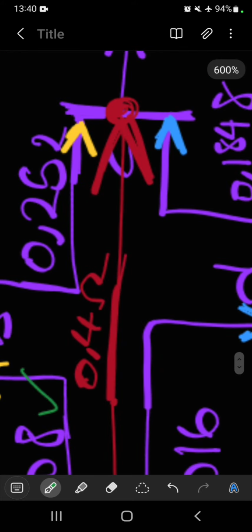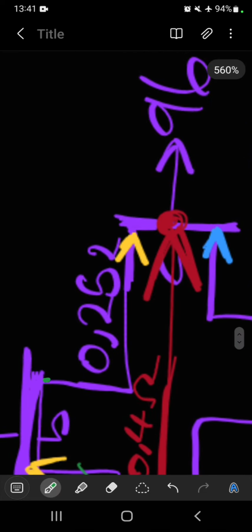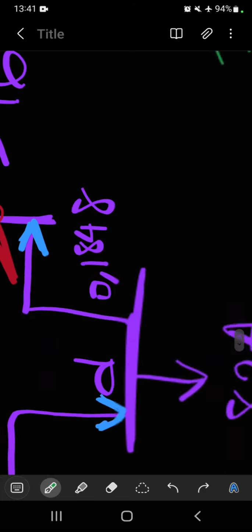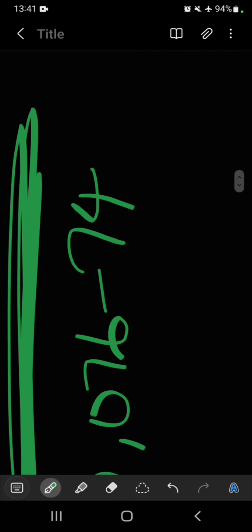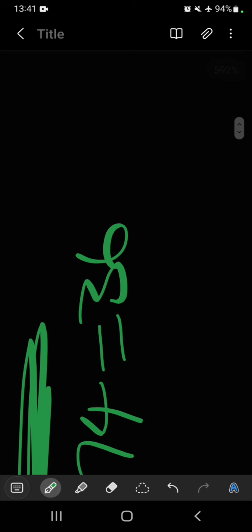So we have IAB, we have IAC. Remember what we said BC is. We said BC is AB minus C. So let's go ahead and calculate it. IBC is equal to IAB, which is now 110,076 minus 74. So I'm just gonna minus 74 there, and then we get our BC as 36,076 amps.